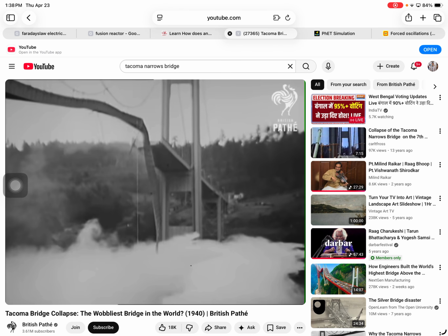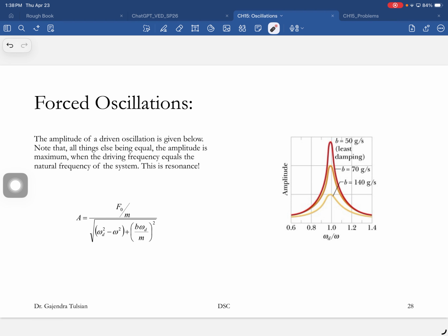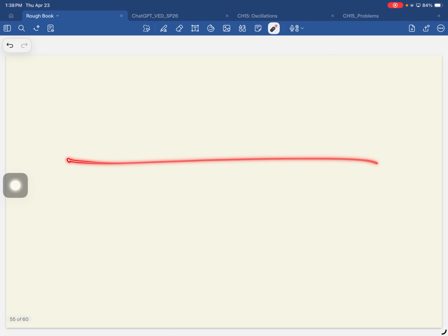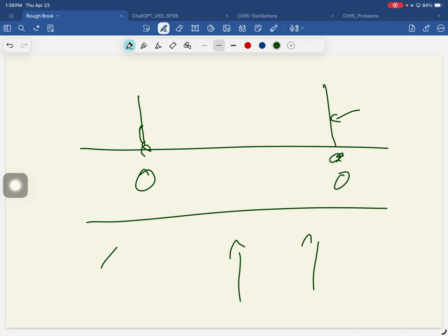So you saw that. What was happening was roughly this. Here's a top view of the bridge, and here are those pillars at the bottom, and wind was blowing. You heard that only 35-mile-an-hour wind, and vortices would build up behind the pillars and break away. They broke away at a frequency that matched the natural frequency of the bridge. So you set up resonance.